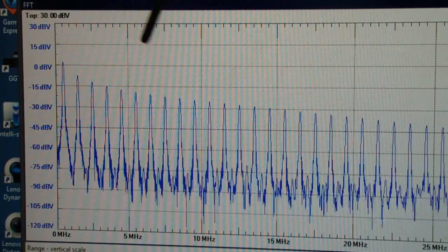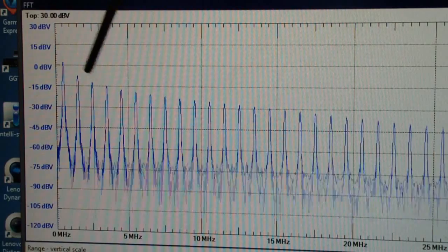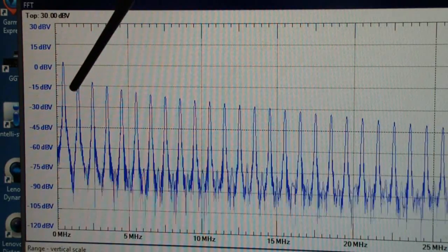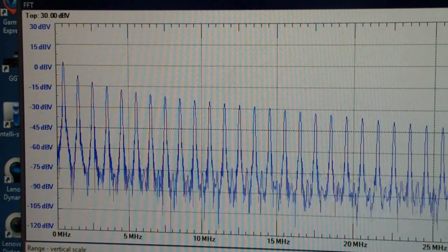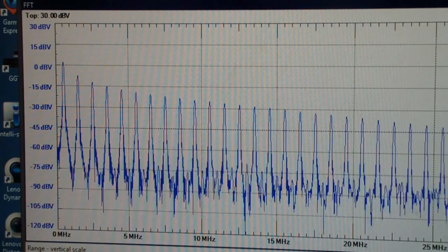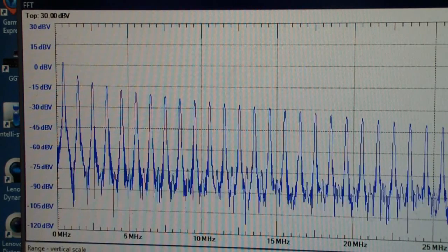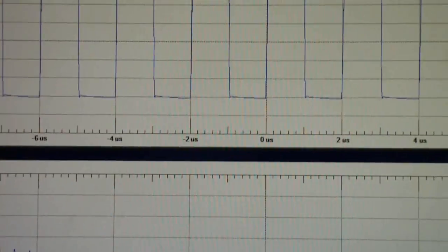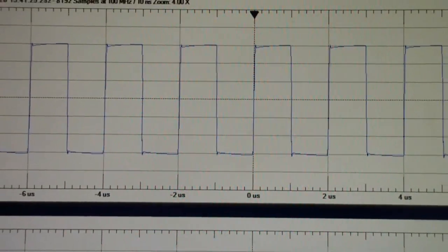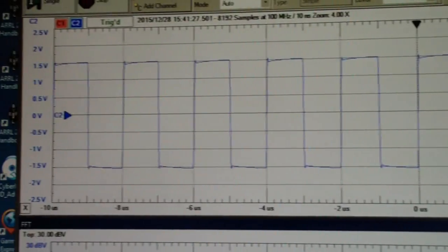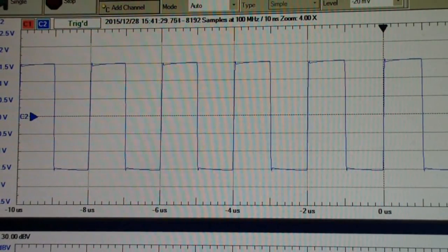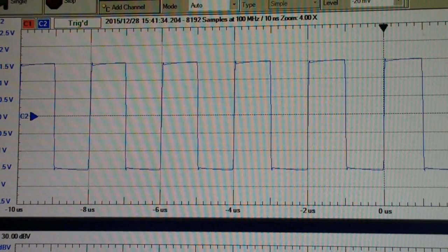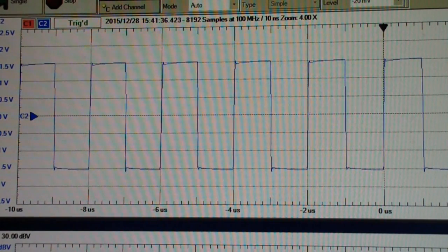In a spectrum analyzer, it's called the resolution bandwidth. And the reason is, I said earlier, that an FFT is actually just a mathematical transformation. It's not actually measuring the frequency. What it's actually doing is it's taking the signal that you're displaying on the oscilloscope itself, or in the case of any of the digital storage oscilloscopes, it's what's stored in memory.